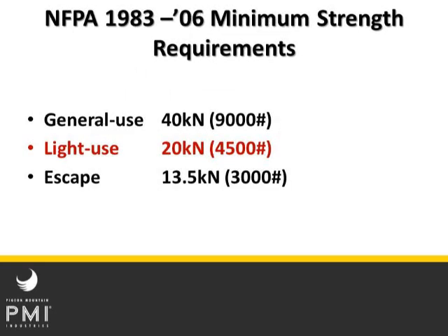Let's talk about what the minimum requirements are. Here's NFPA 1983. A lot of you users are probably pretty familiar with these numbers. General use is 40 kilonewtons or greater. Light use is 20 kilonewtons or greater, and escape is 13.5 kilonewtons.